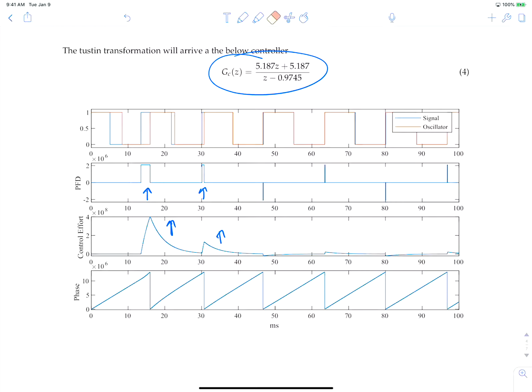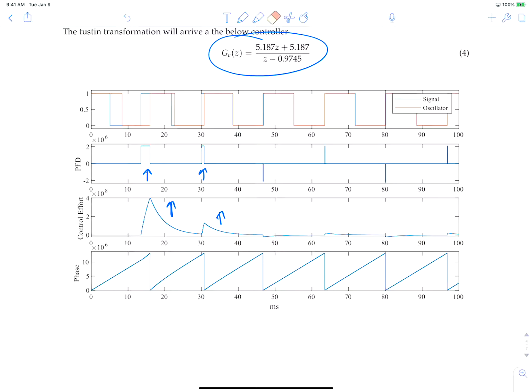And it's one cycle wide, and the cycle length I'm talking about is the sample time, or 100 microseconds. So once again, we are locked here. We're locked from here on forward. From here, this is kind of the lock state. And there's no discernible difference here in terms of looking at these waveforms, whether one's better than the other. They're just different implementations of the same controller.